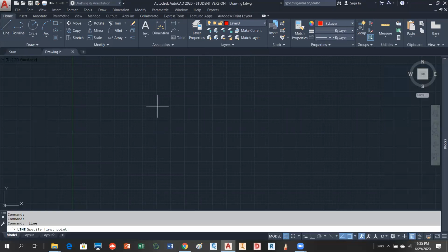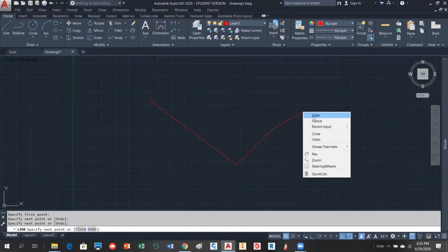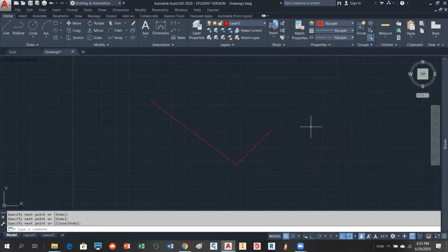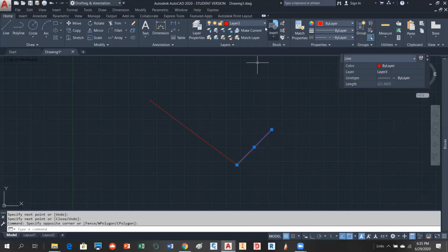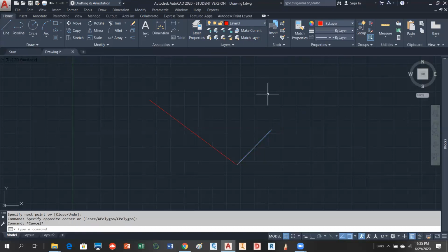And if I get an object on the wrong layer, there's an easy way to move it. Somebody remember how to move it from one layer to another? You just select the object you want to move and then come up here, move it to the layer you want it to go to. Make sure that you deselect it by hitting the escape key, because if it's still active, it can move back to another layer, okay? So that's one thing to also remember, all right?